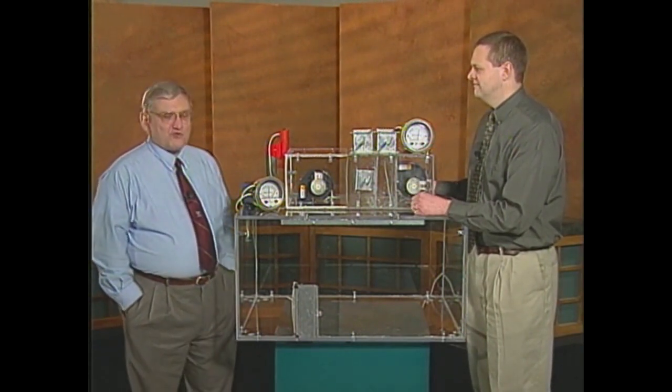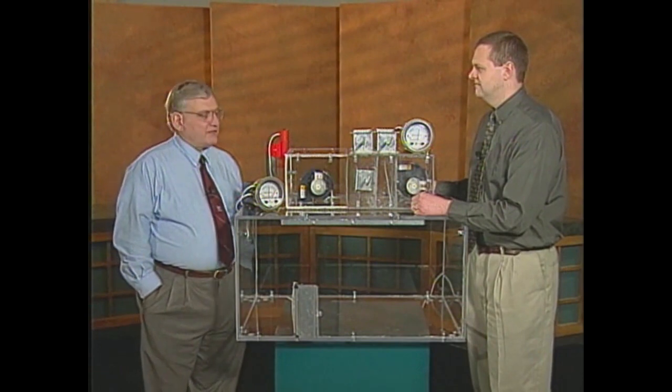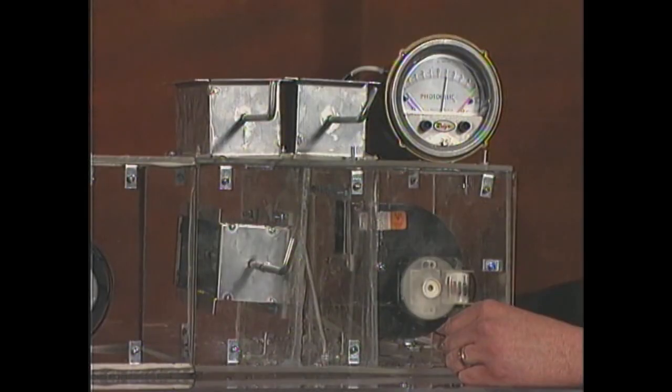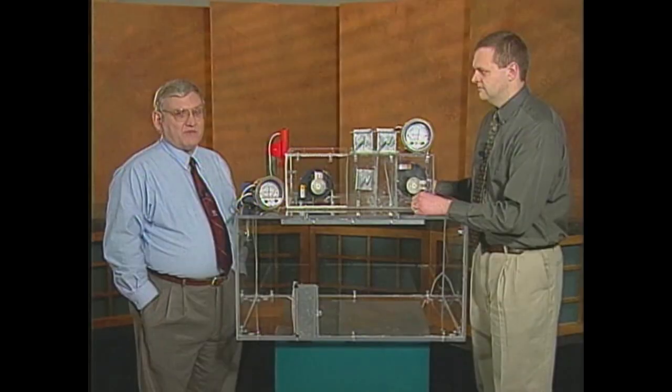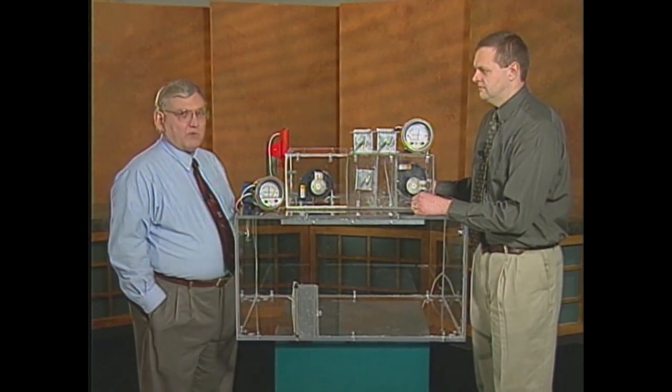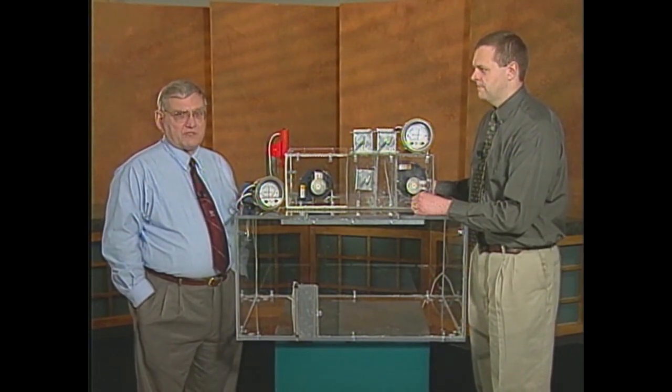Right. Control loop stability and timing are critical. Also, one more key point from an applications point of view. The pressure across the return air damper is relatively high, so it's very sensitive to positional changes. Be aware of that when you're setting up your control system.